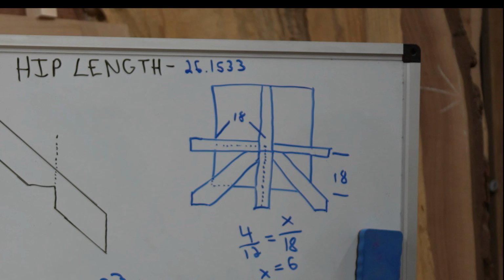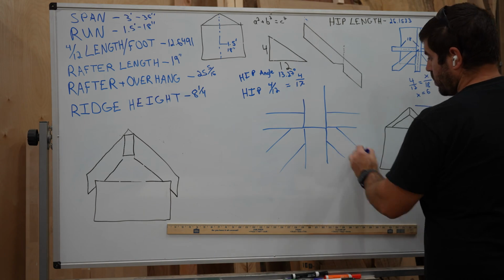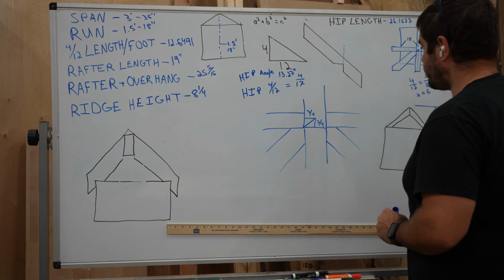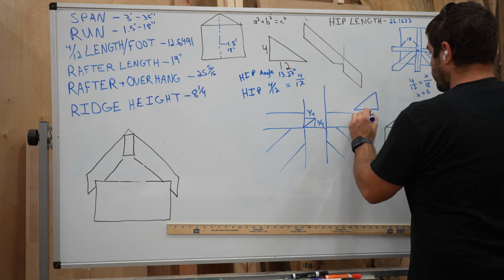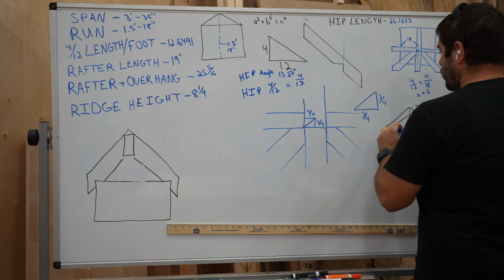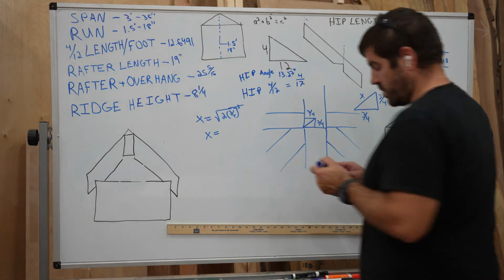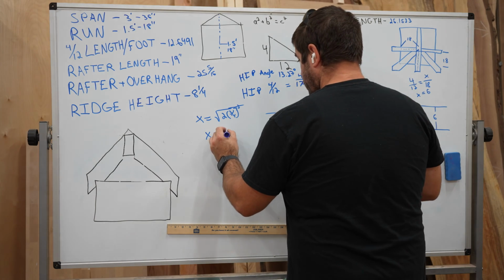Let's go back to the length of the hip rafter. The length we calculated is actually to this point, but as you can see, the hip rafter actually goes only to this point, so we need to calculate first the horizontal distance that we need to remove. The ridge board is 1.5 inches wide, and we only need half of that, which is 3/4. And since the value that we are trying to find is going at a 45-degree angle, that means that both legs of the triangle we are using will be 3/4. So to solve for x, we take the square root of the product of 3/4 squared and 2, which is 1.06 inches.